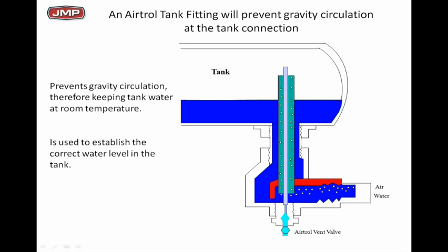It, in essence, gives you a smaller tank because of the air-troll tank fitting. It helps you start it up and get all the air out to begin with and have the proper water charge inside your tank. I think one other side comment here you should recognize in a regular tank: this tank is not full of air at startup. Once you get it started and get the pressures on it, it's going to be partially full of water depending upon the makeup pressure when you start it off. In other words, the acceptance volume in this tank is not going to be 100%. It's going to have some portion of it full of water when you start the expansion process.